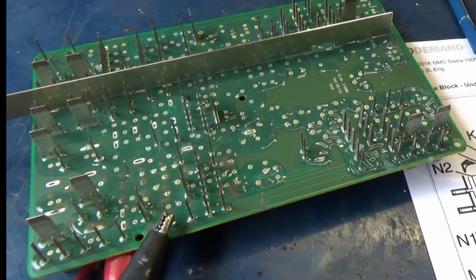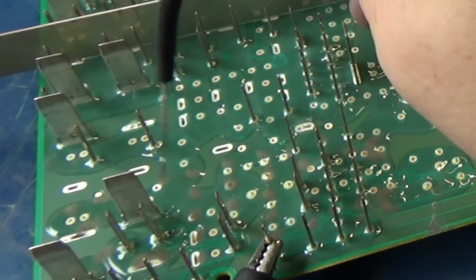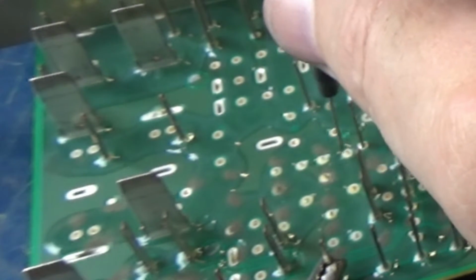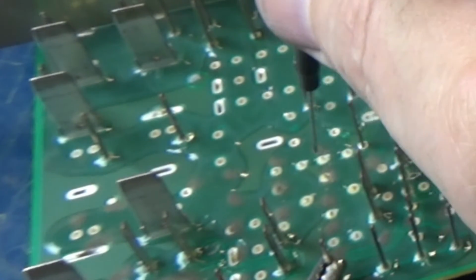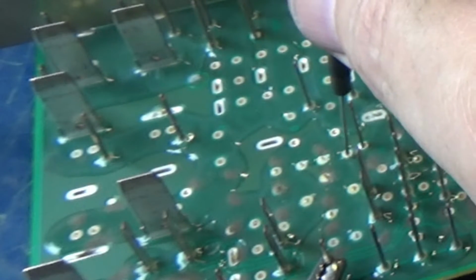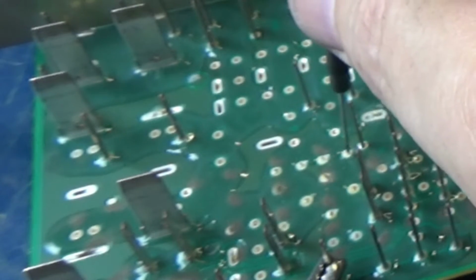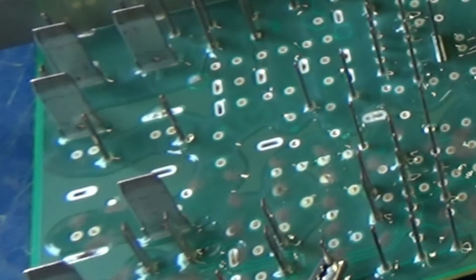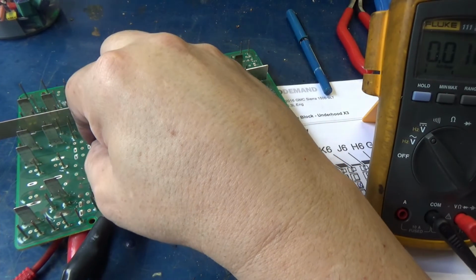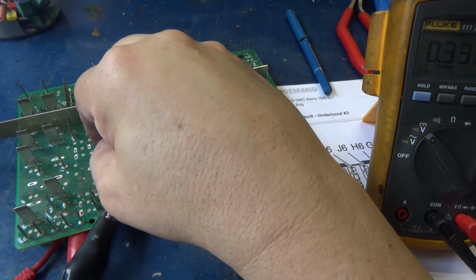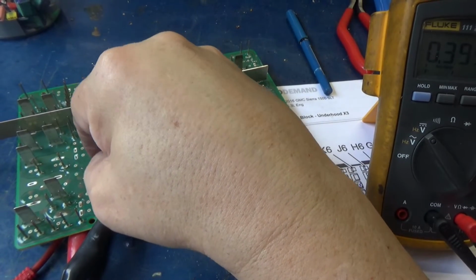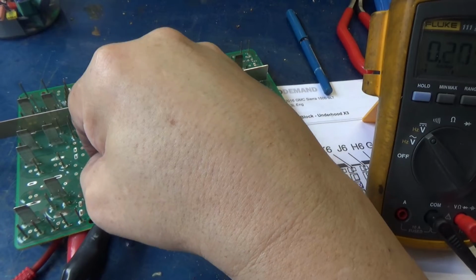Alright guys, so I just verified that these two contacts right here, this one and this one, are the power and ground to the relay that we need to work. And they do have power and ground, but there is no clickety-clack of the relay. Relay is definitely bad. So I'm going to remove this conforming material, I think is what they call this stuff. And we're going to commence to unsoldering.